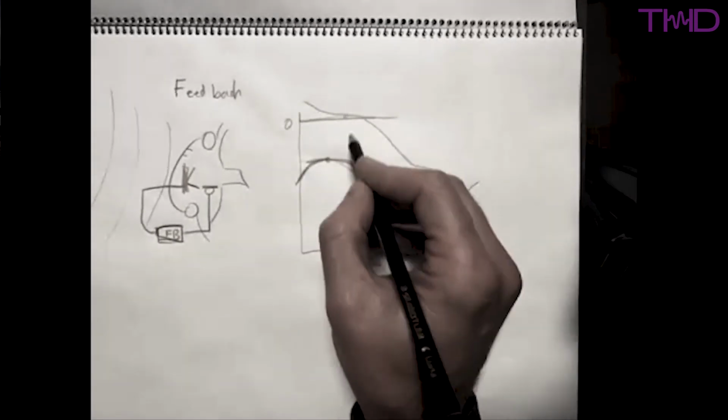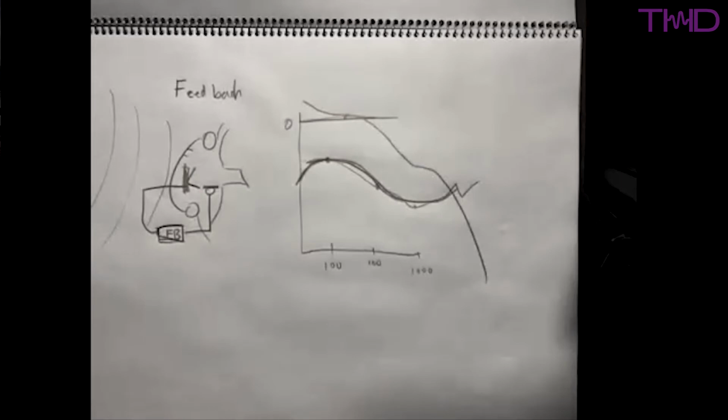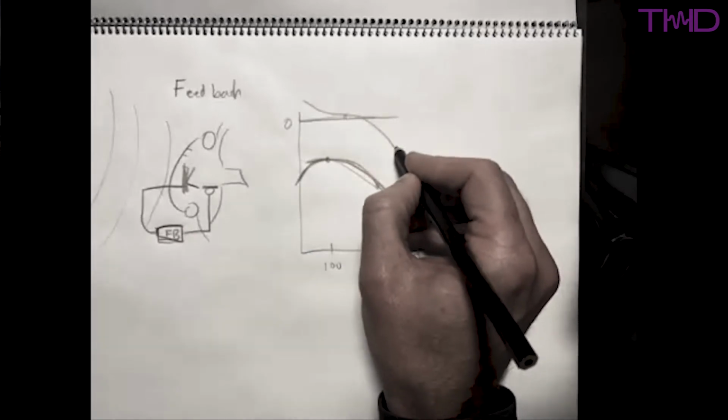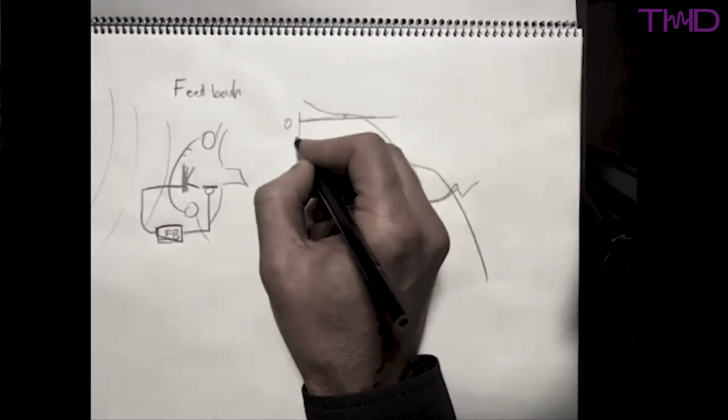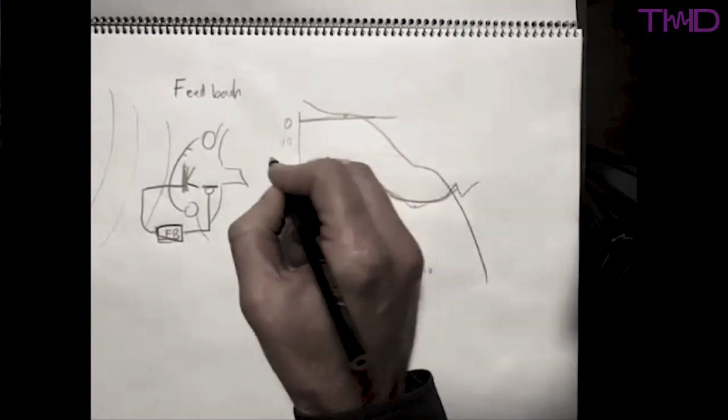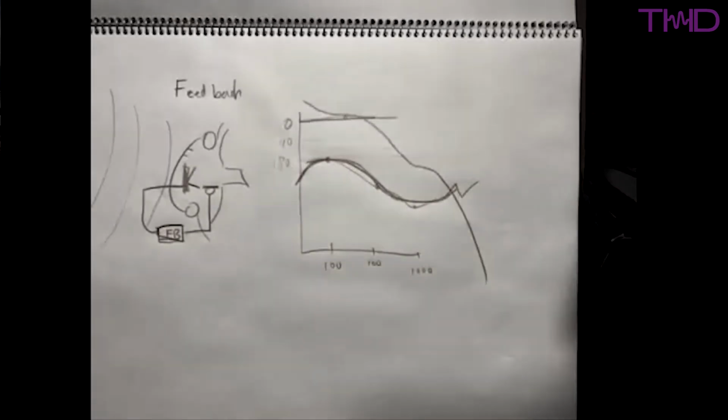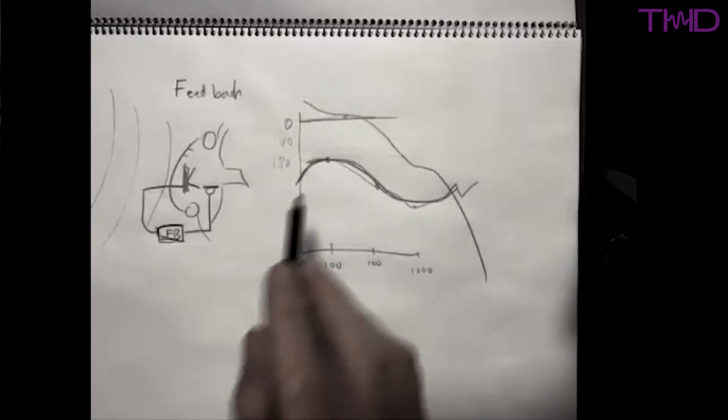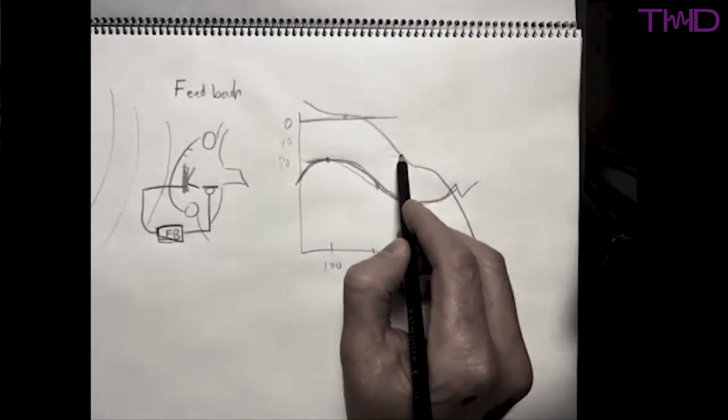If you just had one frequency, you would need to do nothing with the filter. If everything was 0 phase, the filter doesn't have to do anything. You just send that signal back out the speaker. But that doesn't happen. The phase starts to go very negative, and let's say you get past 90 degrees to 180 degrees, which is completely out of phase. At that point, the signals are going to start adding together again, and the thing will become unstable and squeal. So the whole game with feedback is to construct this filter that prevents that from happening.